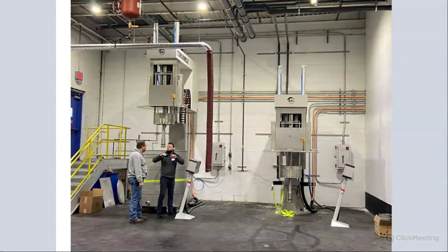So what happens here is this customer is producing a material, a pigment dispersion. He puts the container underneath the TM1000 with all his liquids, and then he's adding the pigment while the dissolver disc is spinning at low speeds, just to get the pigment introduced to the mill base. And then once all the product is introduced, he increases the speed to about 18 meters per second, anywhere 18 to 25, and does that for about 30 minutes.